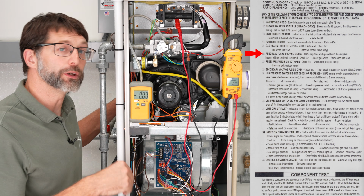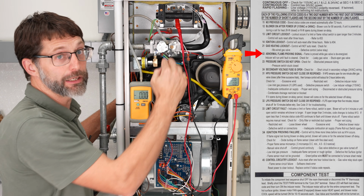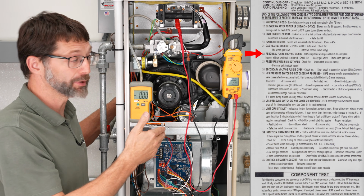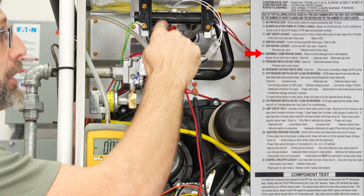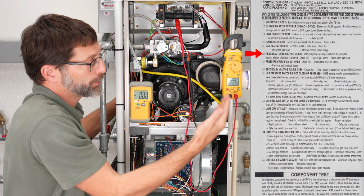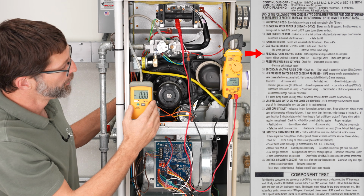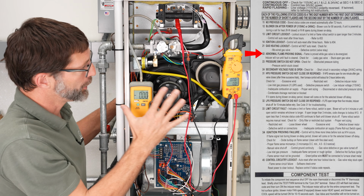Number 22 is an abnormal flame proving signal, which means that there is still a flame up here even when there's no call for heat to turn on. So maybe the thermostat got satisfied, the sequence of operation for heat has stopped, but the problem is this gas valve is internally stuck open, allowing gas to continue to flow through. And so the furnace is measuring a flame rectification signal, say 4 microamps, and so that will be a problem. But in this case, obviously, we don't measure anything right here, so we have no flame rectification signal. We don't have any gas flowing through here presently, so we're good right now.